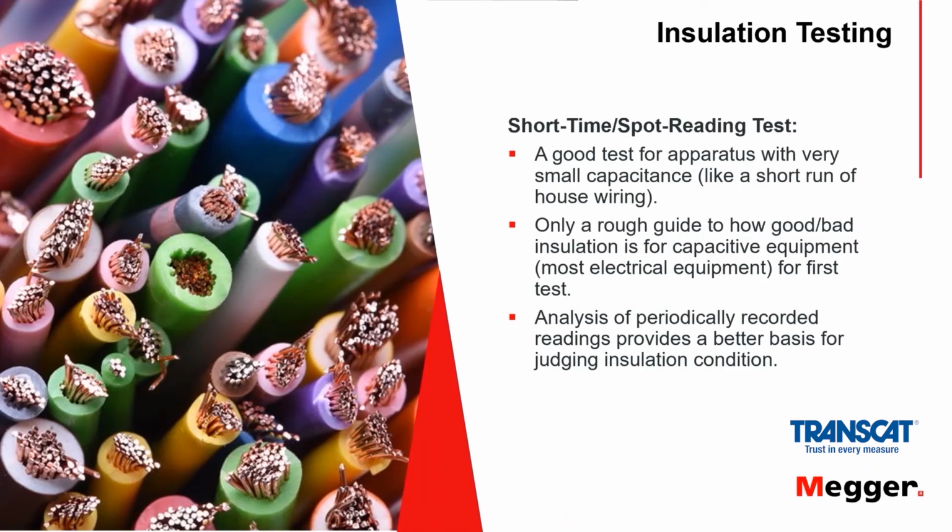The spot reading test is a good test for small equipment because you're going to come to full charge relatively quickly and have your final reading. But other test methods that go into more depth give you more information than you would just get out of a short time or spot reading test. But if you remember, we mentioned early in the webinar go no go type testing, and generally a spot reading test is probably all you need for go no go.